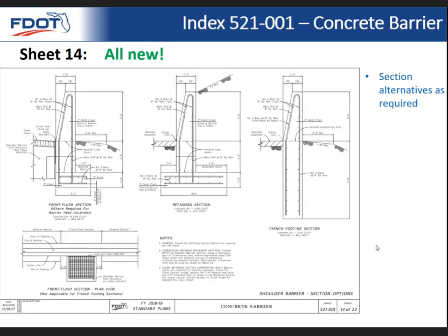And then here are those alternative sections. You can select these as a designer as required. The retaining section here, one thing to note is that the heel has been extended by a foot to help support this soil. And so that's new in the new standard, so take note of that.